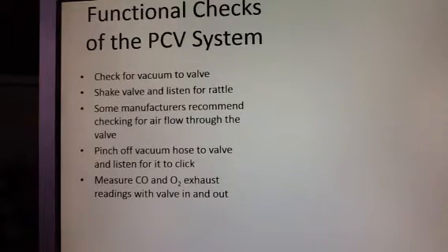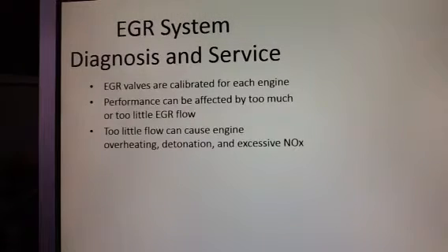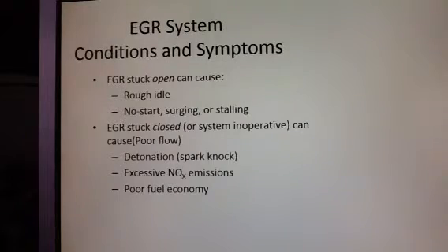With our gas analyzers, we could measure the carbon out of this, so we can look at our CO, and we can look at our oxygen, and we would look at the readings with the valve in and out. Our EGR valves are calibrated for each engine. Performance can be affected with too much or too little EGR flow, and we do have a list of different things here for you on that also.